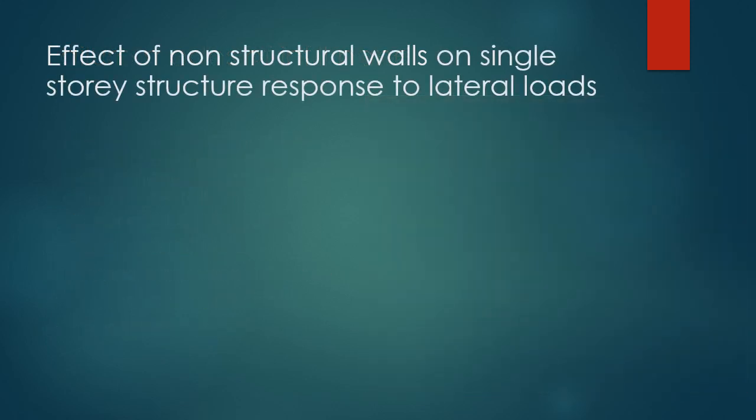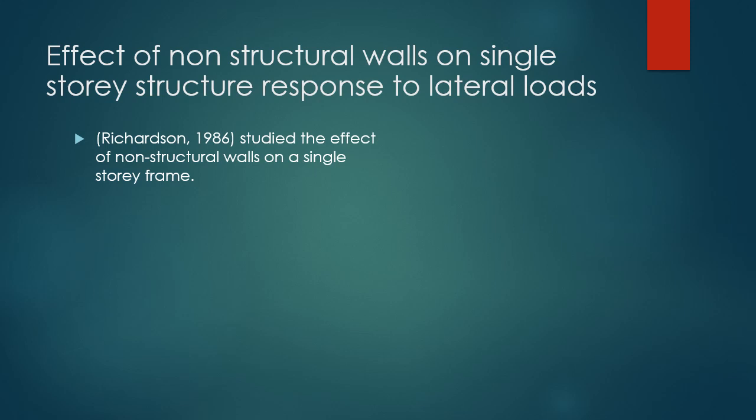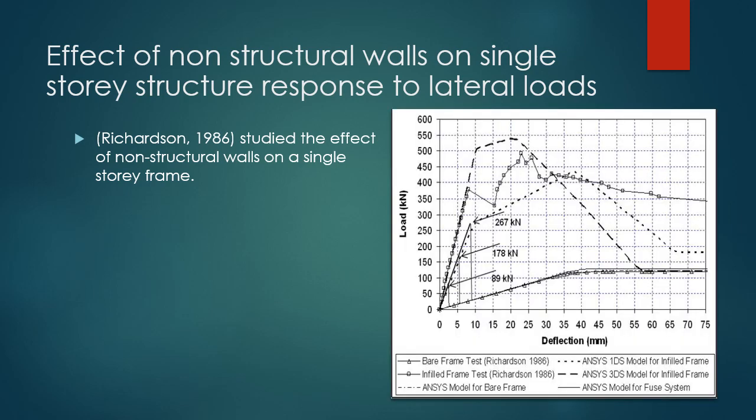First, I'm going to talk about the effect of non-structural walls on a single-story structure. Richardson, in 1986, conducted several experimental and analytical tests on a single-story structure. He then plotted the load deflection curve, which shows that the fully infilled frame could carry lateral load up to 5 times the bare frame.